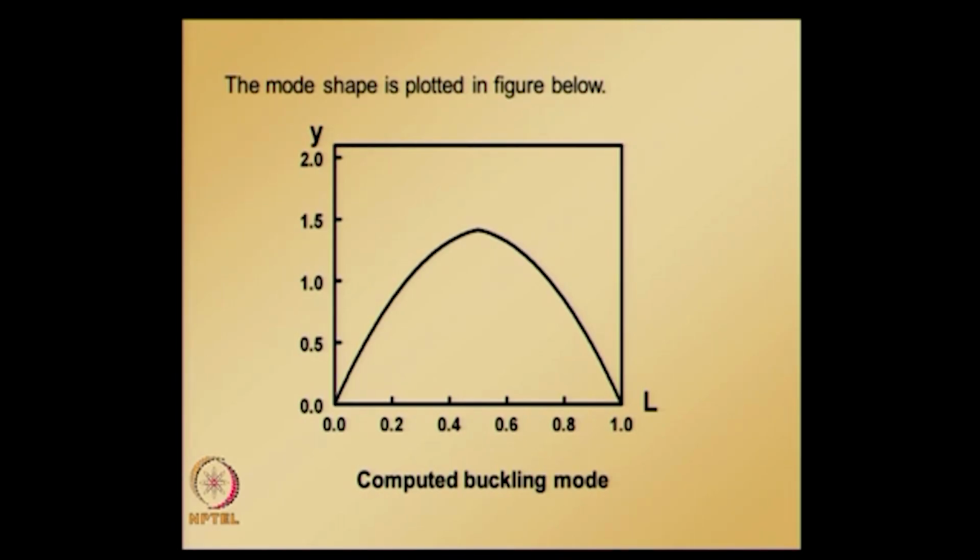So, now we have seen one application of this general one dimensional boundary value problem, which is the column buckling problem, and you have noticed that the evaluation of these integrals when we are solving this problem becomes simpler, because J happens to be a constant. If J is not a constant, then the integrand becomes complicated and we need to evaluate these integrals using some numerical techniques.